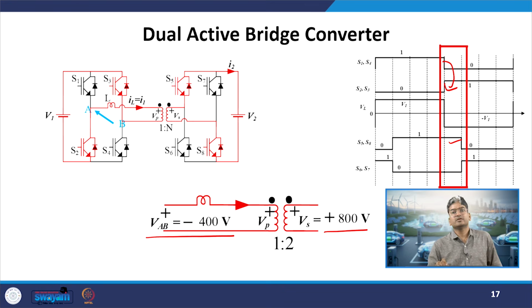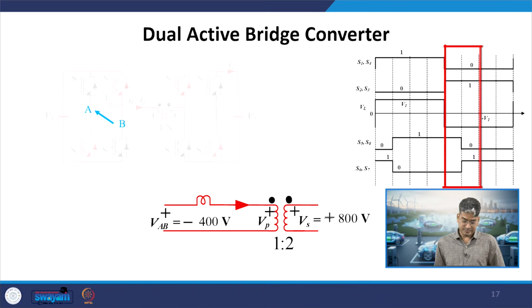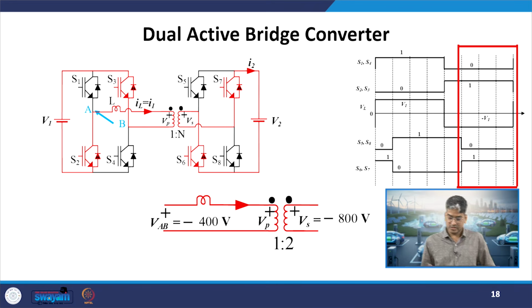So, what are we doing till now? We first fixed the pulses on the primary and secondary side. We have eliminated the primary bridge first, then the secondary side bridge. Now, we will find out what value of voltage will be reflected across the inductor terminals by eliminating the transformer. We are going step by step, so that the circuit becomes simple for us to understand.